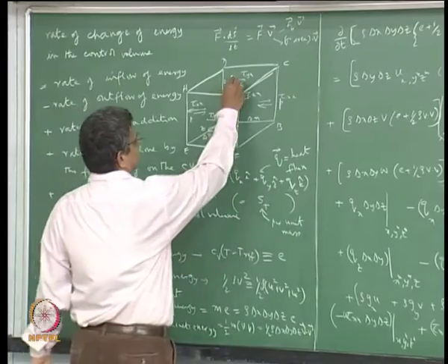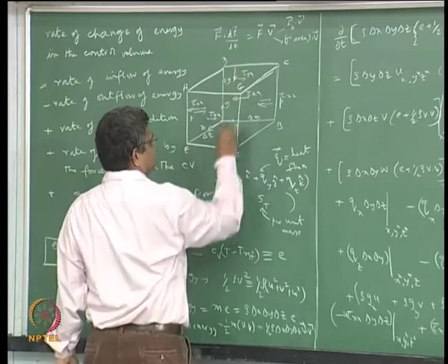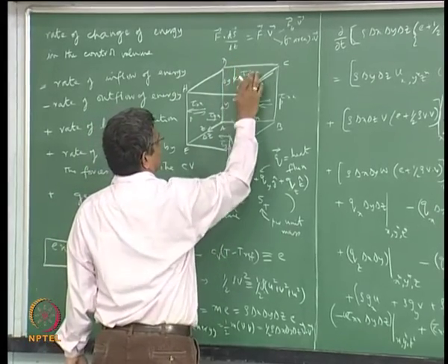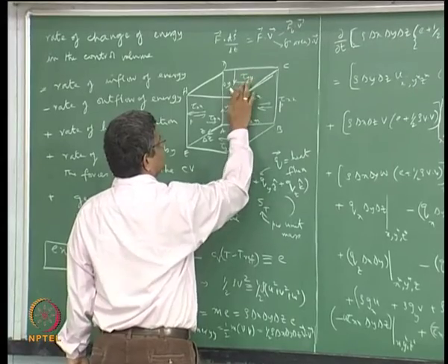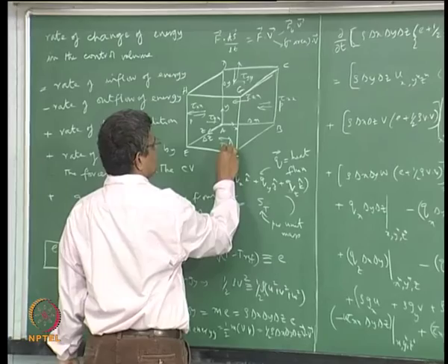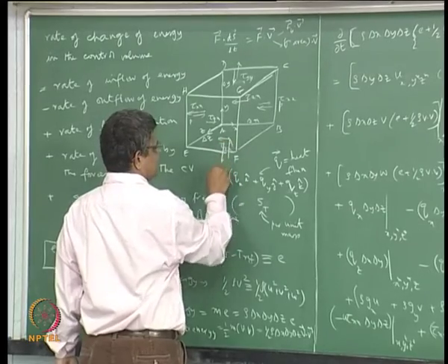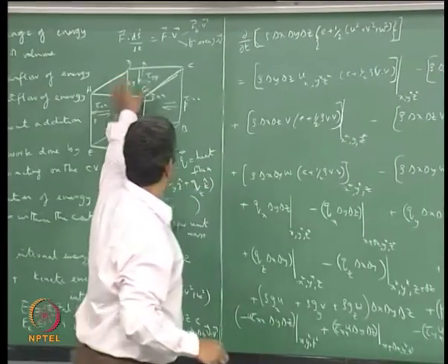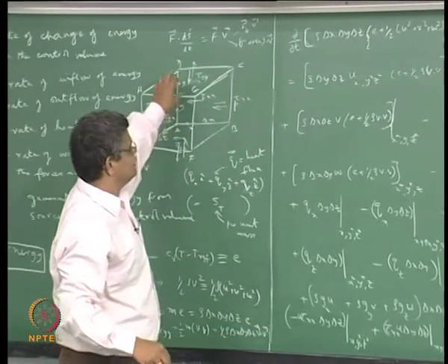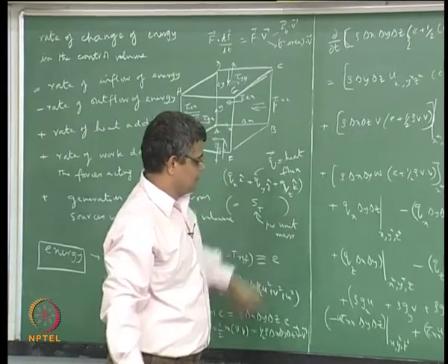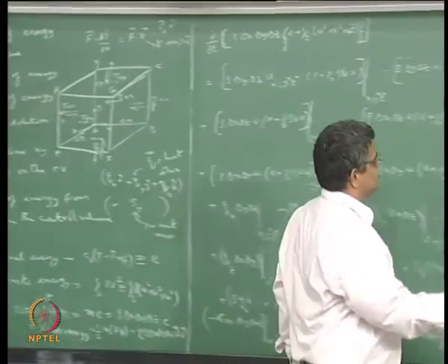So if you consider, for example, the pressure here and the pressure here, and there will be a tau yy acting in this direction and tau yy acting in this direction. So we can write them down, and when we consider all the stresses acting in the y direction, we have to multiply by the v component of the velocity vector. So let us just do that.